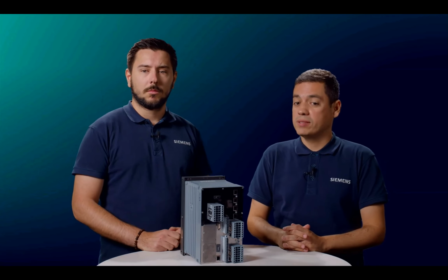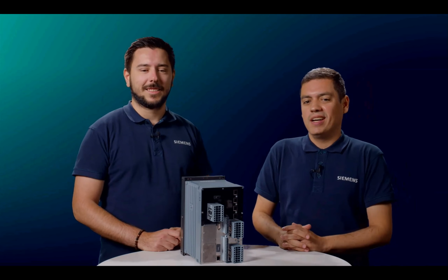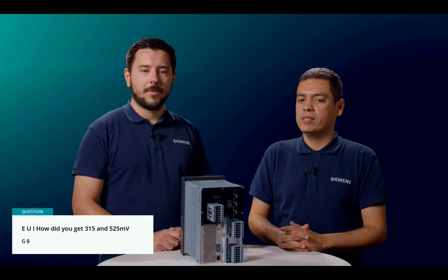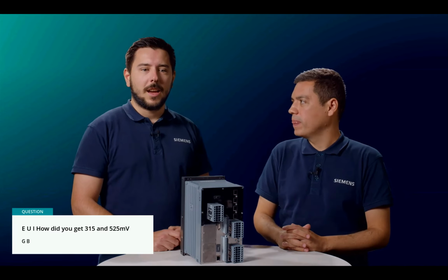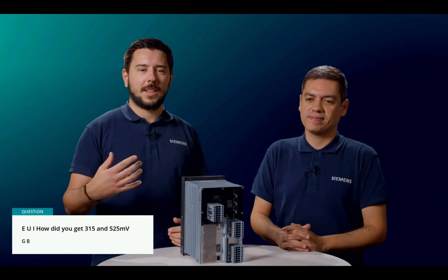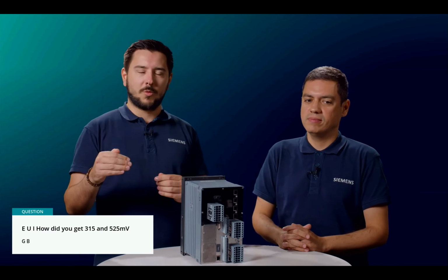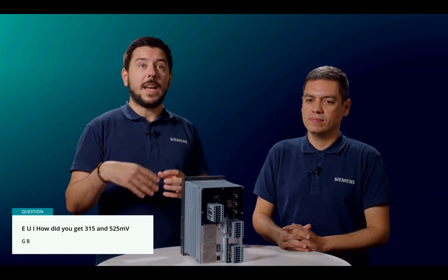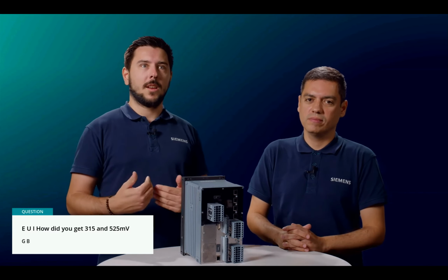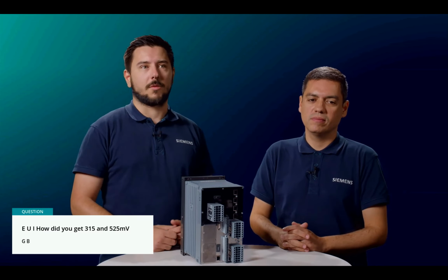And one question, I think related to the calculation that you made about the settings. How did you get 315 and 525 millivolts? Unfortunately, I don't have a whiteboard now where I can show it, but the idea was basically with the sensor rating of 50 amps to 22.5 millivolts to calculate with this ratio what secondary voltage I get when I have a primary current of 700 amps.